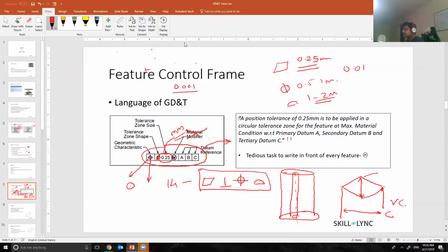But for example, if you consider a knuckle, a knuckle attaches to a link. Let's say it attaches to the toe link. So that joint is very crucial. So in our company, we give that tolerance, the flatness, as 0.1 millimeter, which is extremely tight and which is extremely costly. So it depends on the function of the part. If it's not so much functional, you can give 0.25, which is perfectly okay. If it's highly functional and you want the part to be perfectly rigid, you can give 0.1 millimeter. Again, as you go into industry, you will learn more and more about the numbers. Am I clear?